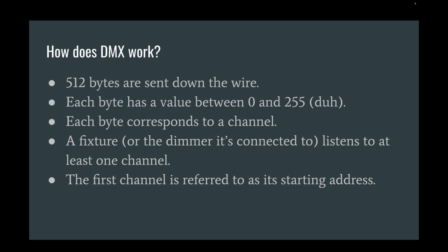The first channel is referred to as its starting address. So, for example, if the first channel for a light fixture controls the panning of it, and its starting address is 26, then 26 would be the first panning channel, or the first channel.